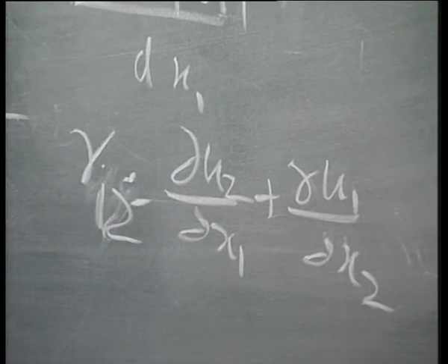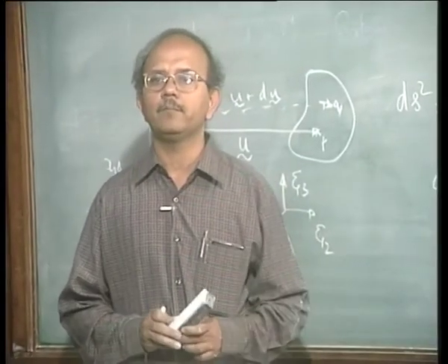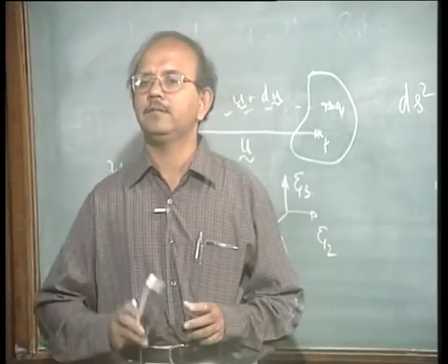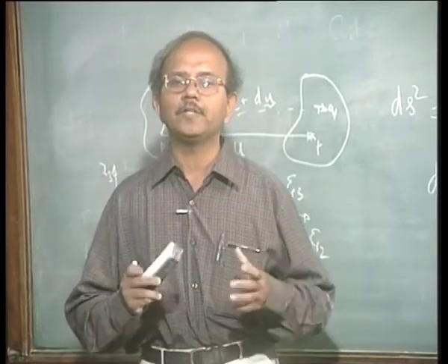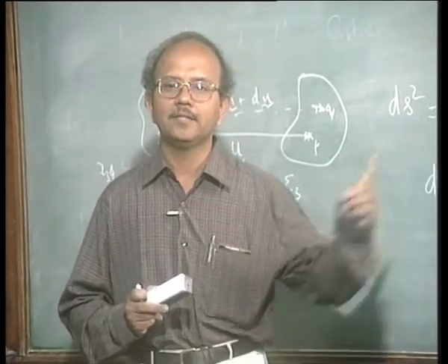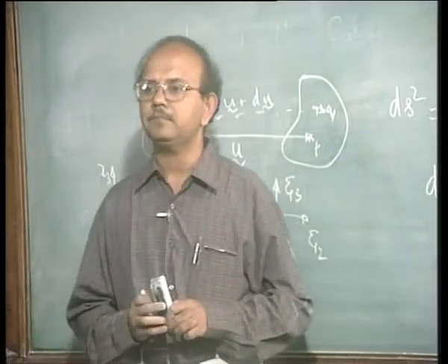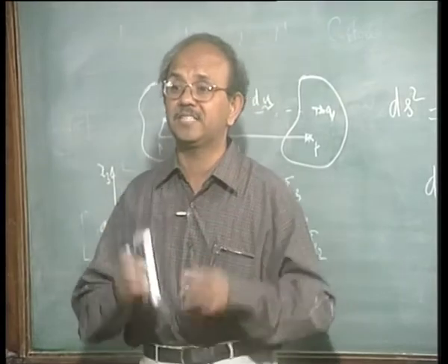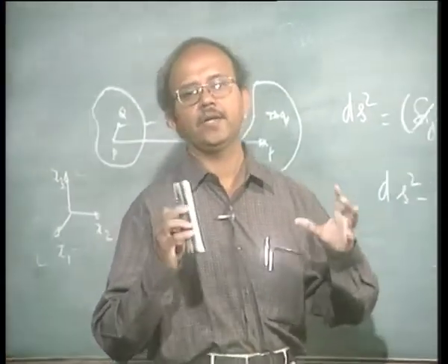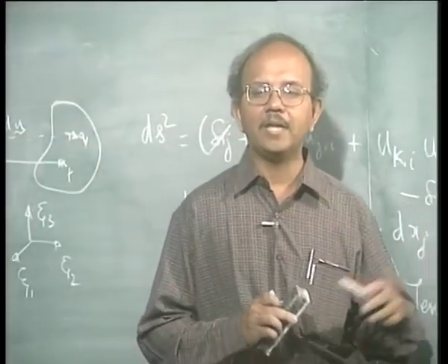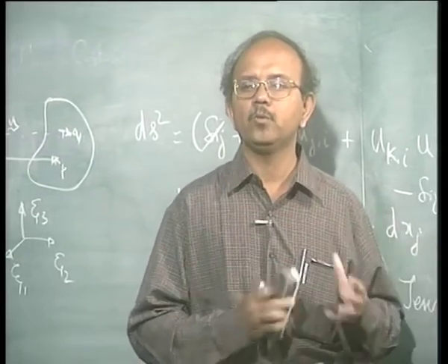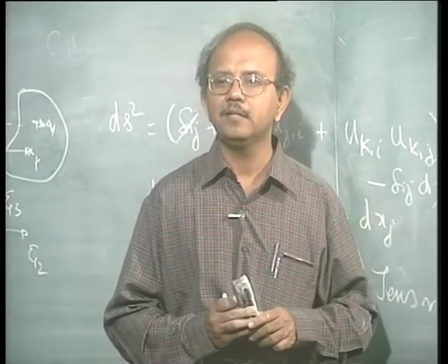Ku is equal to F. So, what is it that you are going to solve? You are going to solve for displacement. Afterwards I have to get strain. How do you get the strain displacement relationship? And what is our next step? Stress strain relationship. Let us be as rigorous as this so that all our definitions can be very nicely written down.